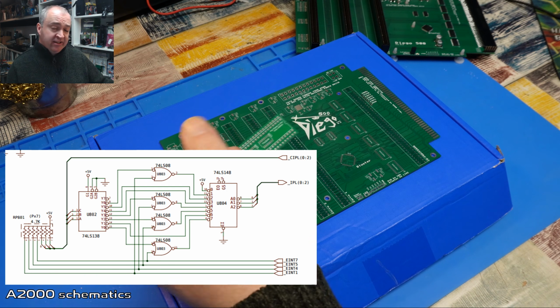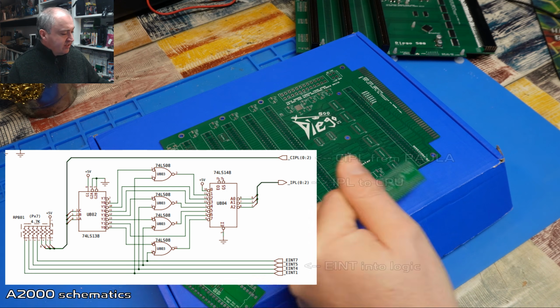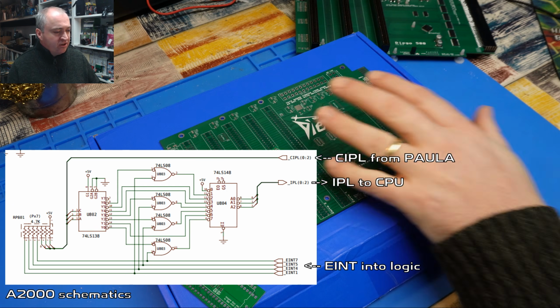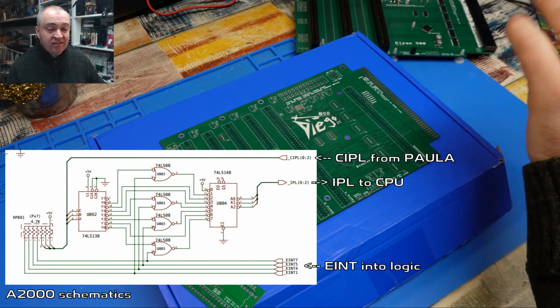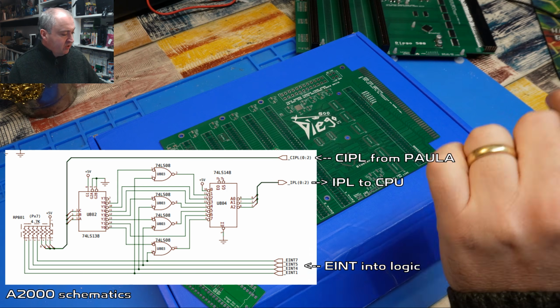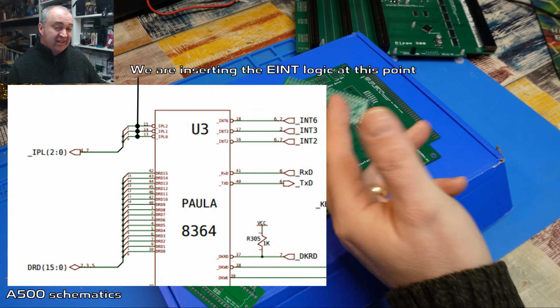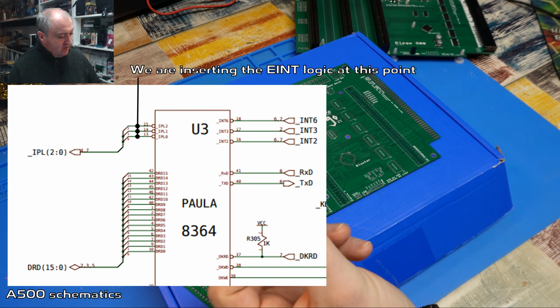This will sit in line with Paula, because the extended interrupt lines, well, they seem to get muxed in along with the IPL lines in the Amiga, which are generated by Paula. So I think that's the best place to put this.